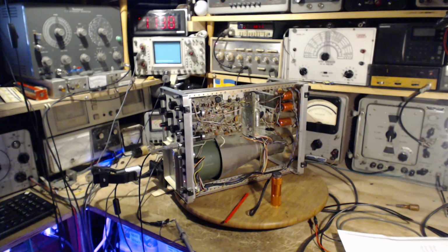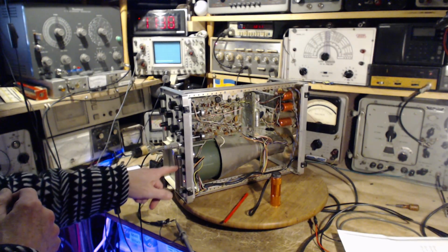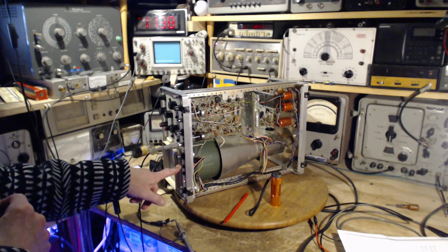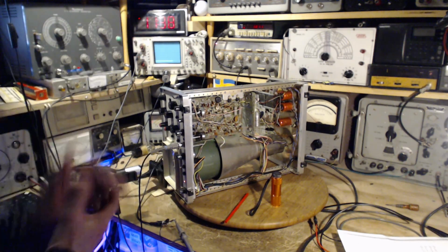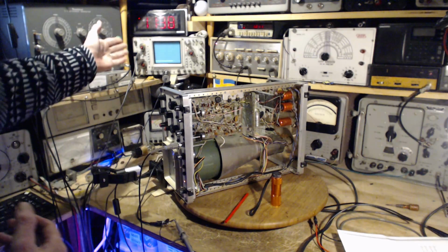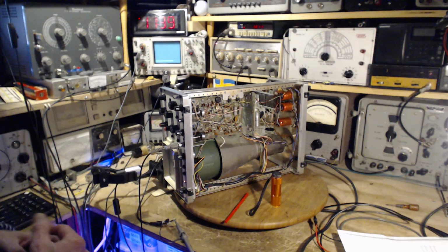So the next calibration is the actual calibrated output adjustment to make sure this is what it's supposed to be. I already know it's a little bit wrong, or at least I think it's a little bit wrong based on using the other scope, which it could be wrong. The assumption in the manual is that I have a 1 volt standard here that I can use.